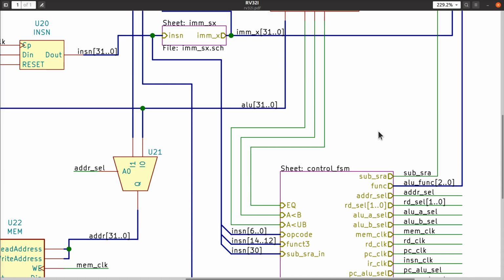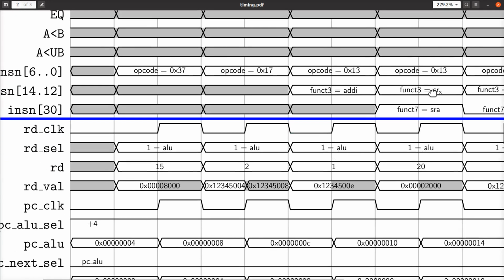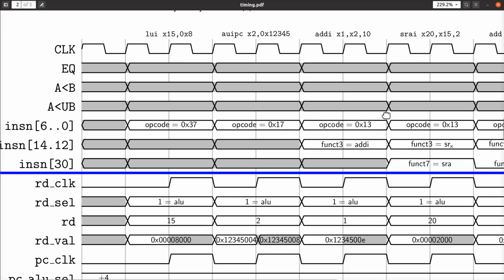in the instruction itself. When it comes to the add immediate instruction, the func3 field does matter, because all the I-type instructions have the same opcode. We mentioned that before. Sometimes the func3 says, I got an I-type that is an add, other times I got an I-type that's shift right, and so on. We already looked at those guys, okay? So what happens for this add immediate?